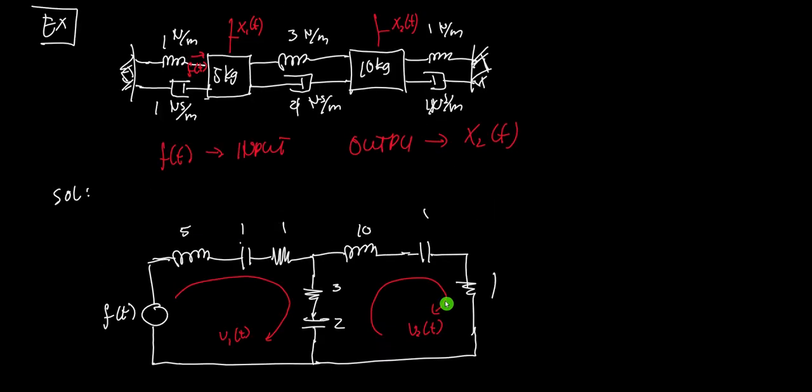And I also want to change my output here, because I put my output to be the displacement. So instead of the displacement, why not just use the velocity so that I will not convert this anymore in terms of the displacement. But if you want the displacement, it's just the same. You just need to take the integral of this velocity here, and that will be the displacement. You just need to change them in terms of displacement.